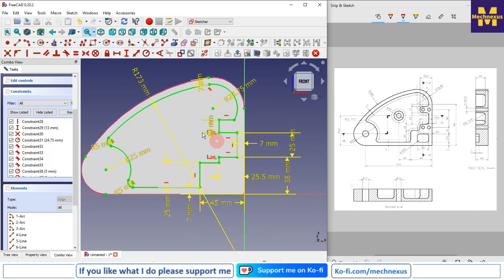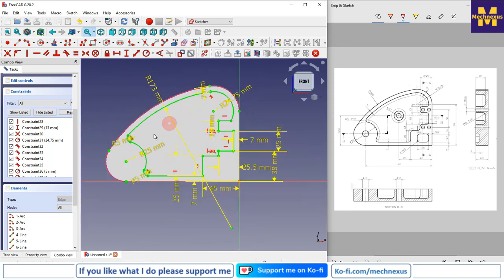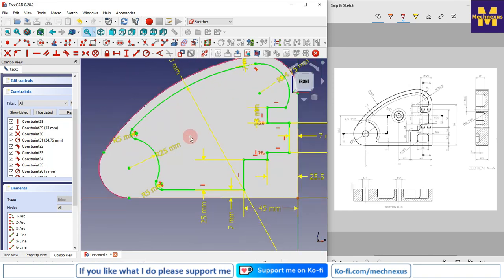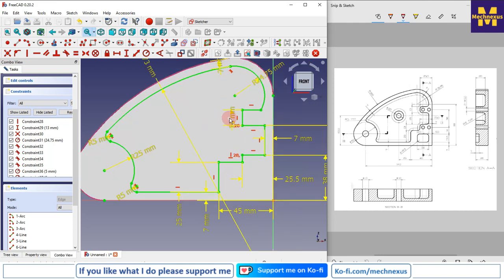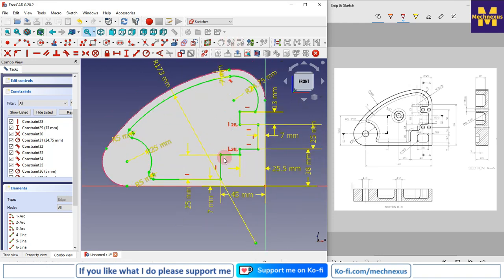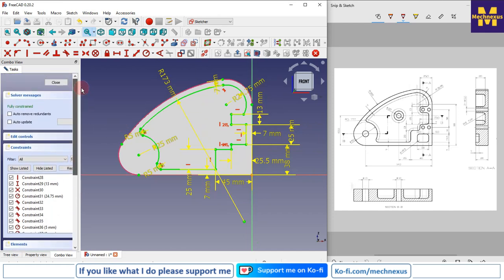So sometimes it is very hard to constrain, because you have to figure out where it is over-constraining or which constraint is missing. So do it carefully while constraining the sketch. So I think it is a very good example of sketching in FreeCAD. So our sketch is fully constrained.